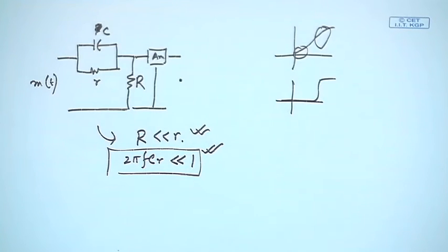So, I will bring the high pass cutoff frequency very close to 0, so that the higher frequency is getting a little bit amplified, and the lower frequency is getting a little bit suppressed. It is not completely getting suppressed. I do not want a high pass filter which is like this, because then the lower frequency, which is the actual message signal, will completely be gone.